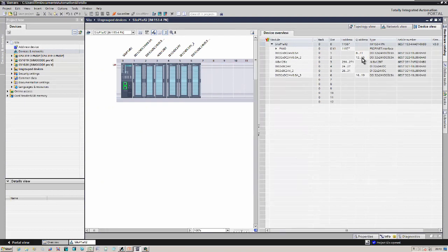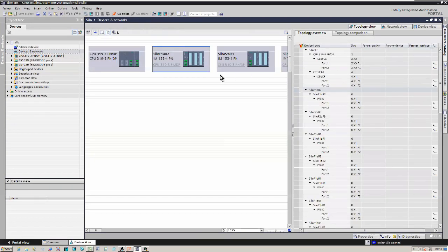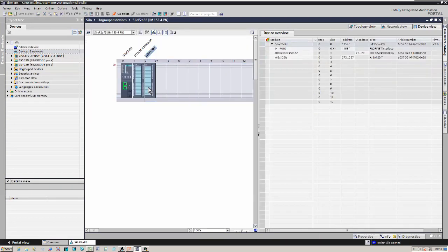You can see we're still stuck to the same numbering convention, 256. It's the first analog input card. There must be another rack with 0 and 4 there. But we always try and start at the same address every time. I go back. That's interesting. See, this one now is at 76. So you can assign them differently, as this is now a plant which has been upgraded.